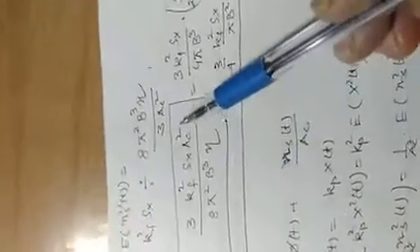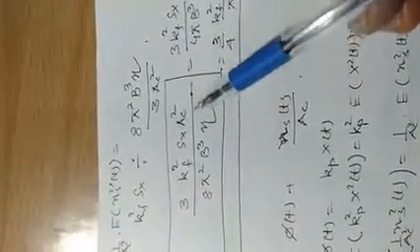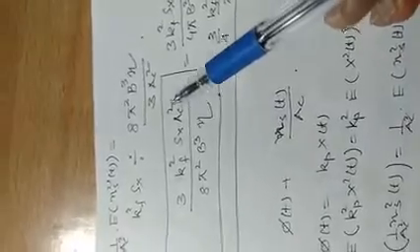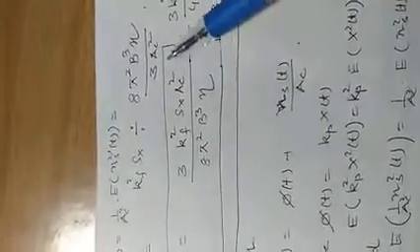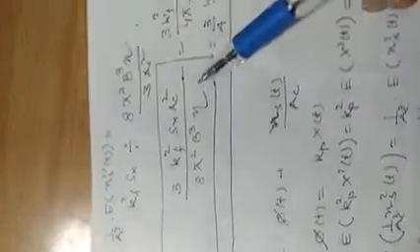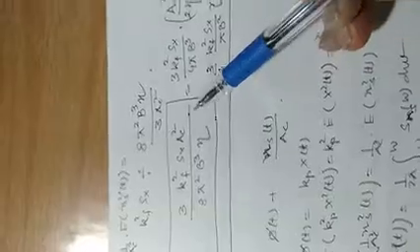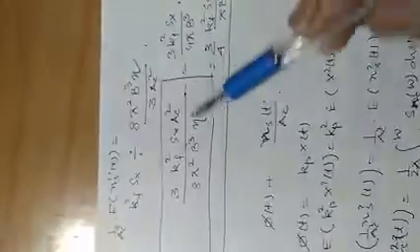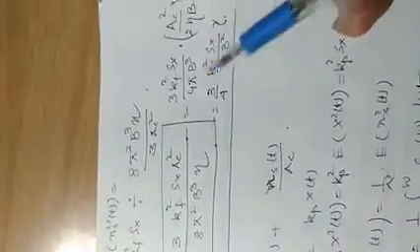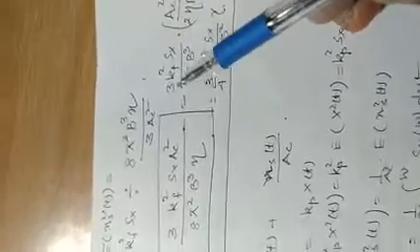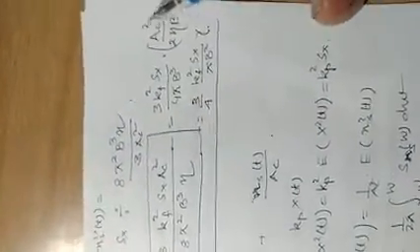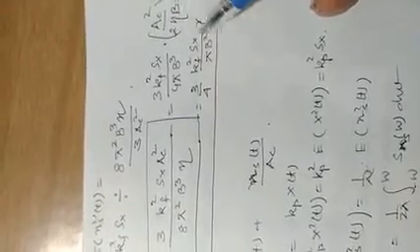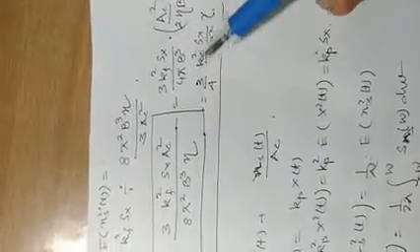And if we take into consideration the baseband system, then the input signal to noise ratio Ac square by 2 eta B is referred to by the gamma factor. So we can separate it and write it in terms of that gamma.